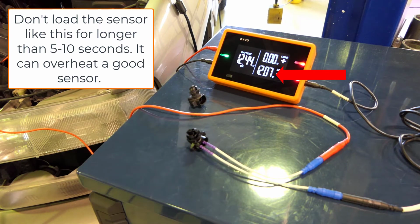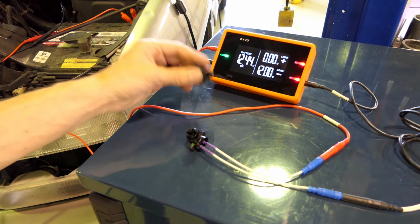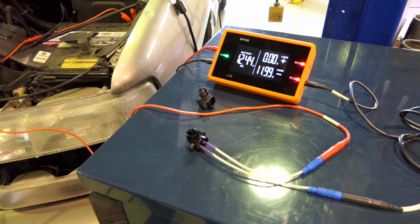That value will slowly drop because as we pass current through there, we're changing the resistance, so it actually kind of thinks in a way the temperature is changing. This is how this sensor works. The temperature changes the internal resistance. That resistance changes the voltage drop, and that's why we see that voltage drop decreasing. But again, much different than what we saw from this temperature sensor. Very clear that that one is defective.